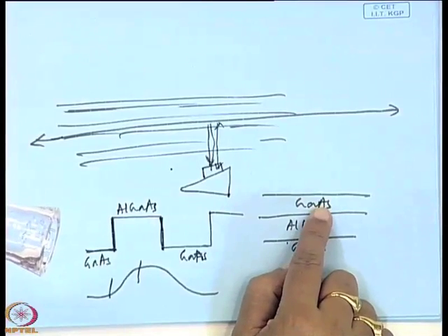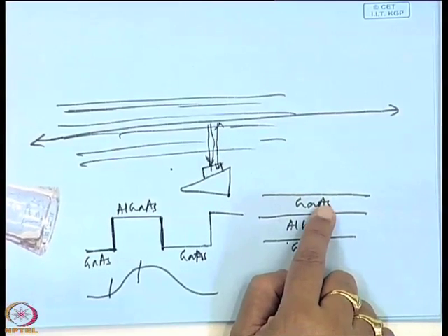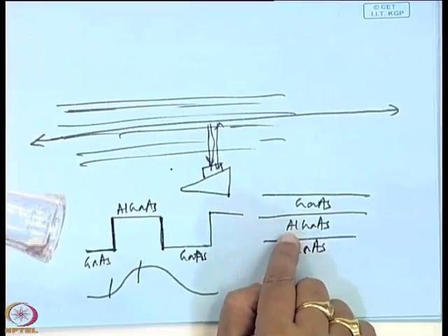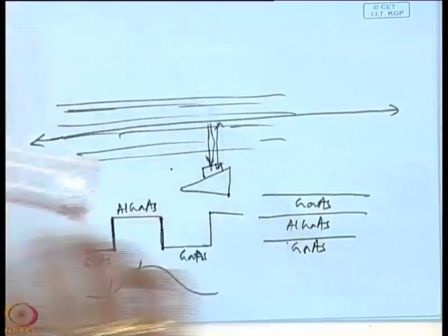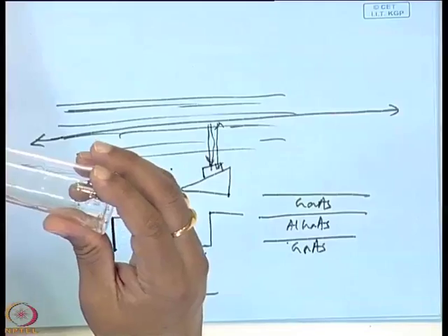Similarly, there are many sharp edges in the reactor. You can see there are many sharp edges on the reactor. On those sharp edges, there may be a trace amount of material, say aluminum. So, when you undertake this growth, from aluminum gallium arsenide to gallium arsenide, what will happen? This trace amount of aluminum will be there inside the reactor chamber, because intermediately you cannot clean the reactor unless the whole growth is finished.